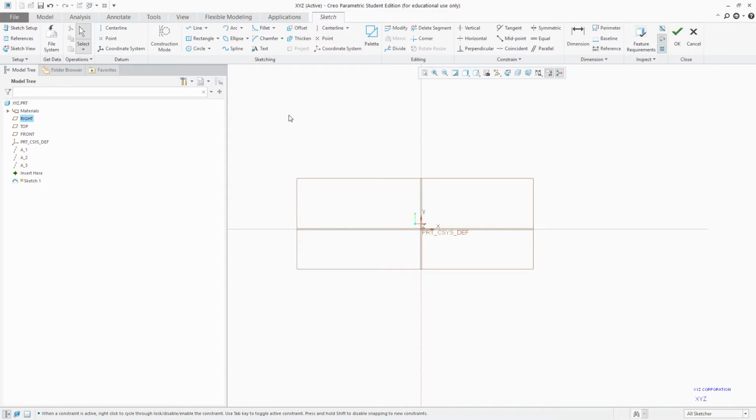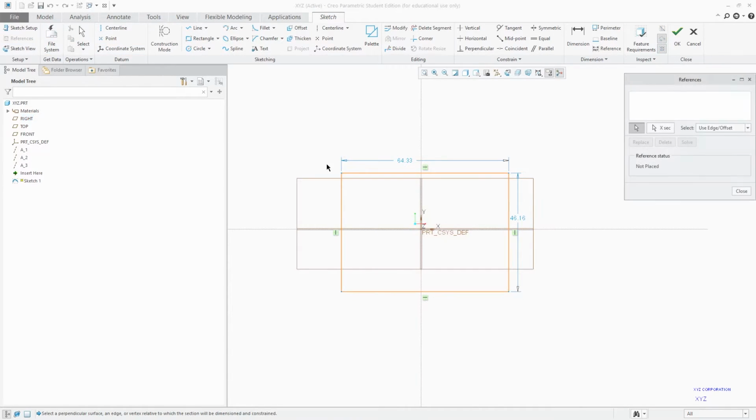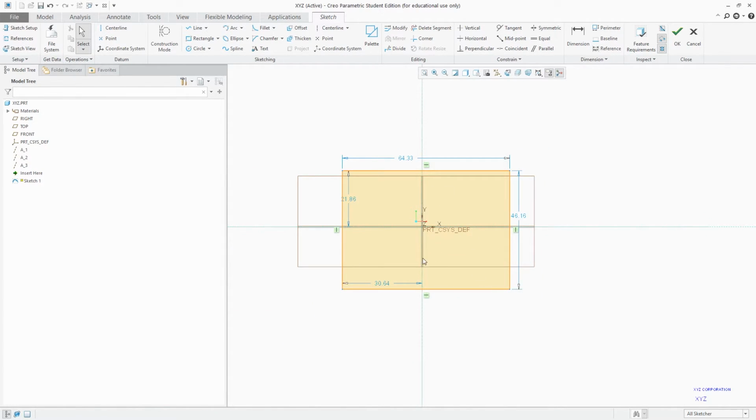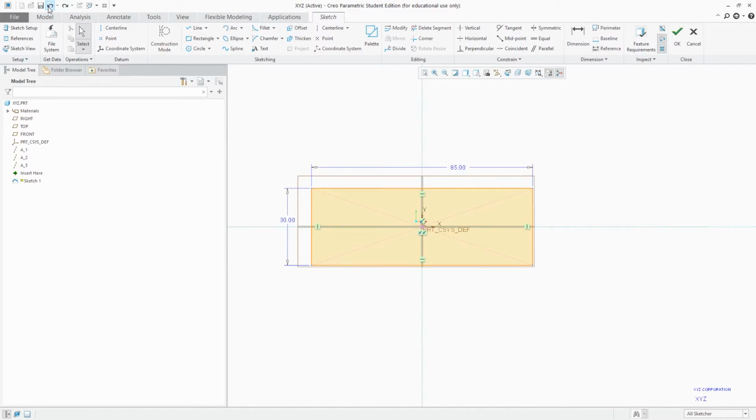and let me just show you the difference between corner one and center one. Let me create references again, one reference and another reference. Okay, now you can see here we need to maintain 4 values, but in case of center rectangle only 2. Now it is symmetric also, so it is quite easy to manage and control compared to corner one.